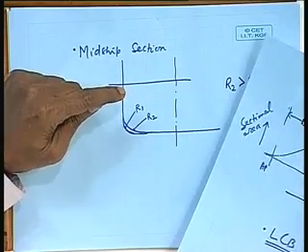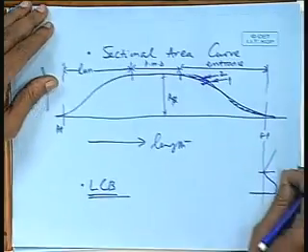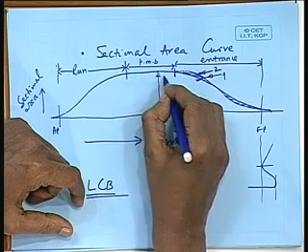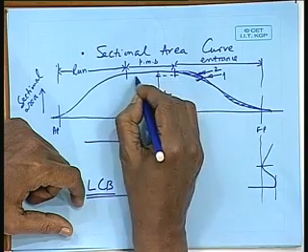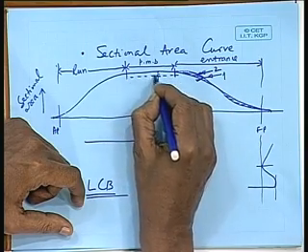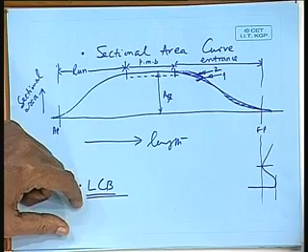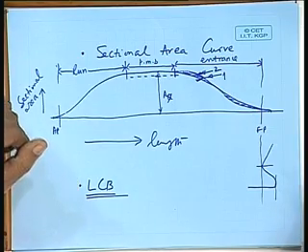Now, I think that if I have a larger bilge radius, flow around the bilge will be smoother. So, I give a larger bilge radius, my sectional area will drop, but I want the same volume. So, if I drop my sectional area to here, let us say, how will my curve change?